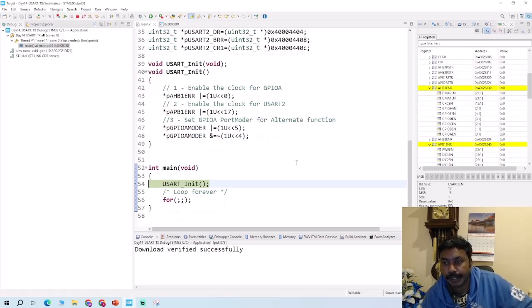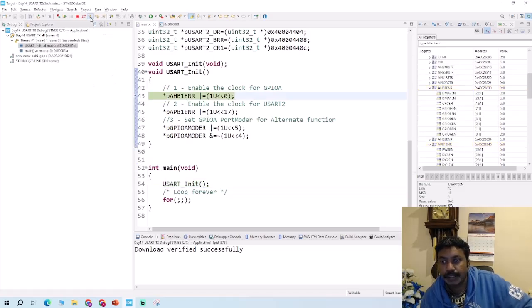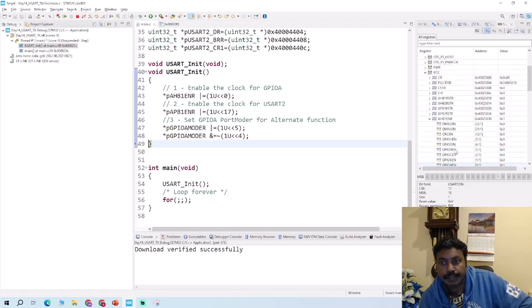Okay, we are in, and I'm going to run step by step so you can see this port change, because we're using this GPIO enable as port mode. So I'm going to step in. See that the clock is enabled, GPIOA enable, and then come to APB1, the next step. Now if you see, this bit will change. We are in the RCC register.